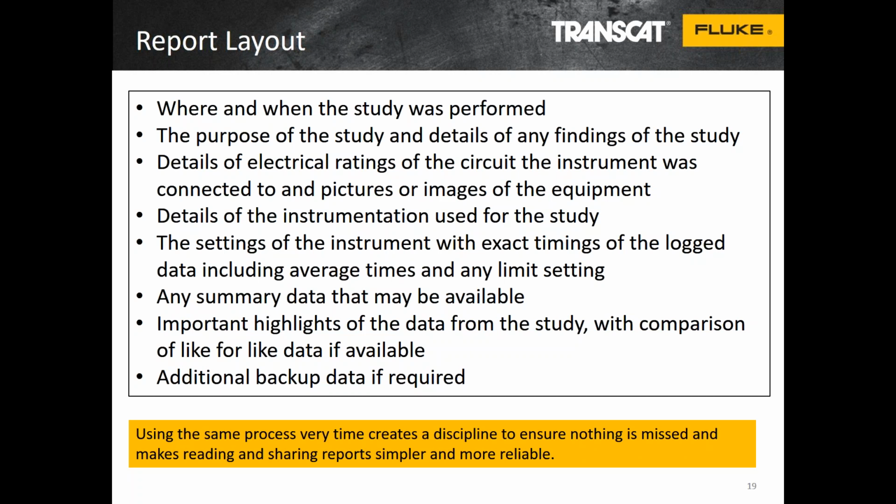If you're doing a short study, a quarter-second is great. But if you're doing a long study, you should always be thinking in 10-minute periods, because that's what the power quality standards around the world suggest. Nothing's really happening that much in a period less than that. There may be dips which are captured in a different way. It's not that you're going to miss those, because you measure without any gaps, but for power data and that kind of information, 10 minutes is just fine.